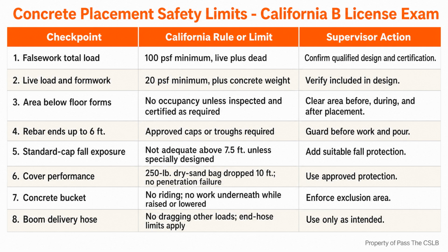The simplest memory rule is ticket, test, then place. Ticket means I confirm the delivered mix and recorded information against the approved documents. Test means the required slump, air content, temperature, and strength specimen work happens at the proper time with the required special inspection. Then place means the site, falsework, rebar protection, access, pump, buckets, and labor are ready before discharge begins.